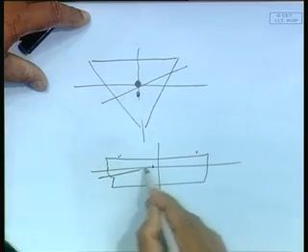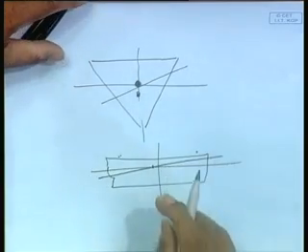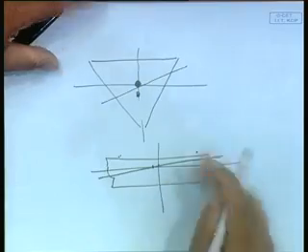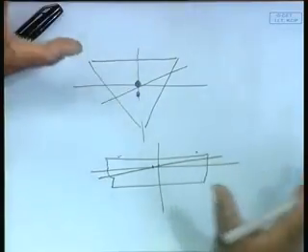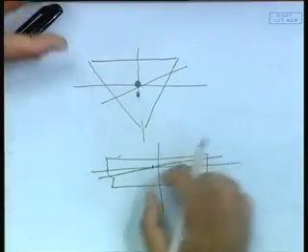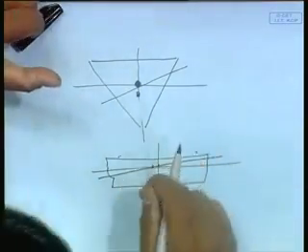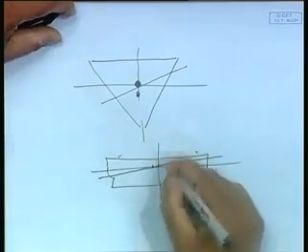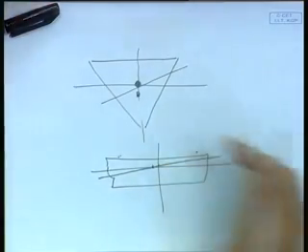One cannot say that, because the trimming happens about the LCF position, while draft is measured typically at some other location, midship or so, and there the draft is changed. So, what I am trying to say is that if I take the draft to be a measure of heave, then if I give a trim, I also have a heave,